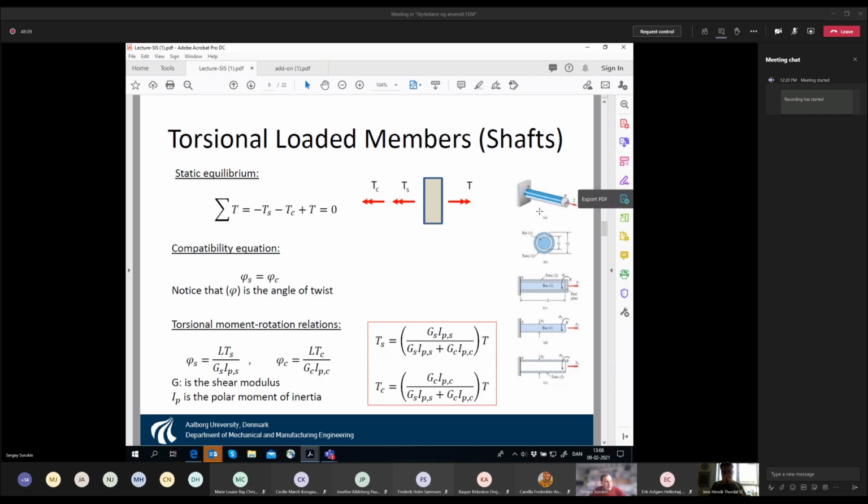You see, we have the same composition, but now the difference is that this structure is exposed to the torque, so that we have this lead now kind of welded or glued to the cylinder inside and the tube outside, so that we apply the torque. And then we know for sure that the rotation angle for the cylinder is exactly the same as for the outer tube.